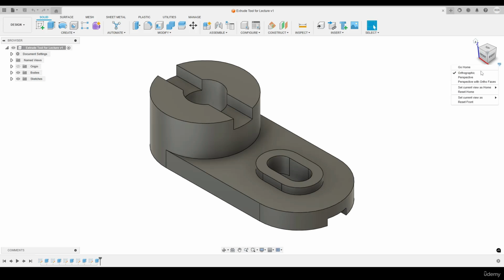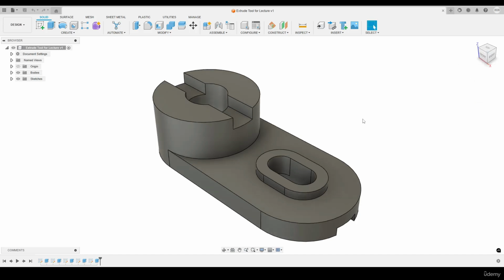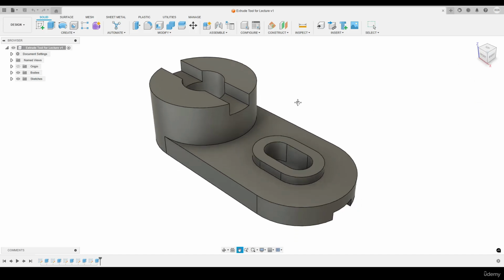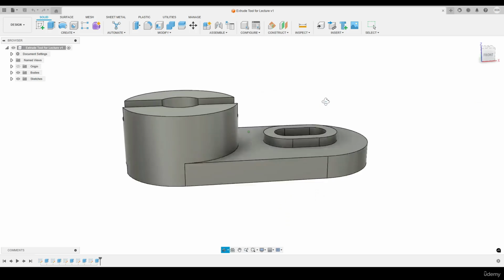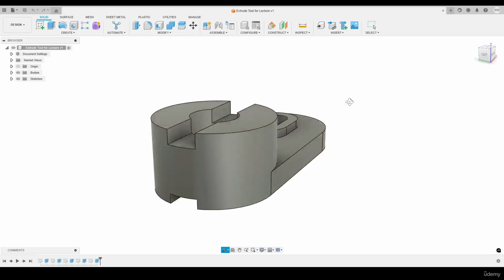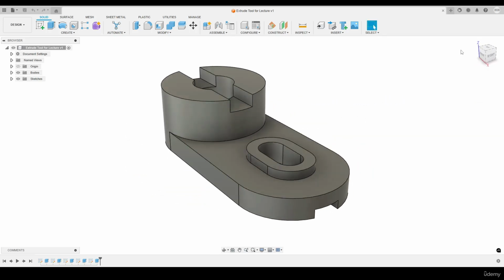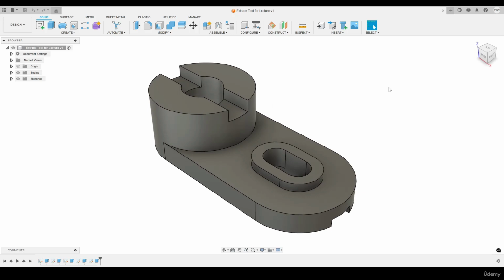If we select that, the very first 3 options that we have are the types of view that we're seeing. For example, typically when modeling, we work in orthographic. For me, that's preferred. But some people would like to use perspective. So I've selected perspective, and as you can see, the part looks different. It looks somewhat more 3-dimensional and realistic. And this can be a really useful tool if we need screenshots of our models or assemblies, we're sharing these with clients, or we're doing them in presentations. Perspective can be nice for that.